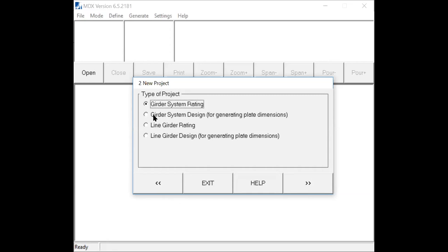This option sounds very convenient, but it never works perfectly because the auto design function is not smart enough and usually generates unnecessary changes of flange size and web size. So although it sounds pretty good, in the real world we don't use this option, because the auto design result is not the ideal design.